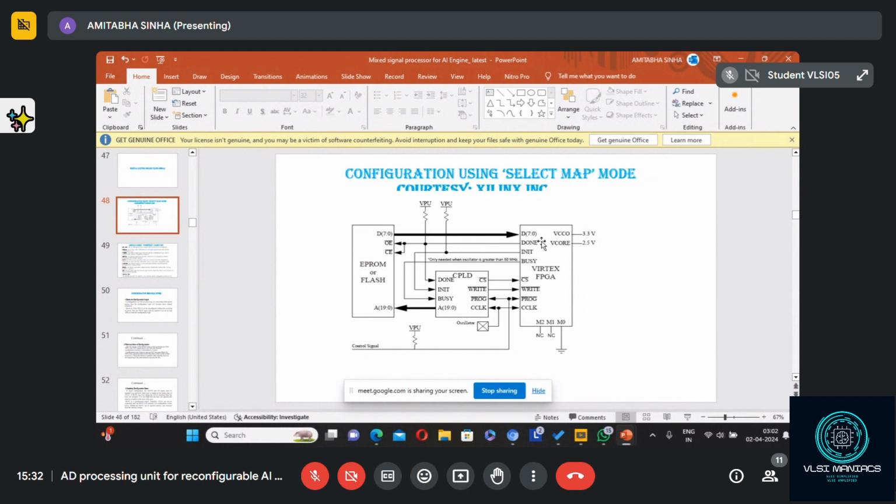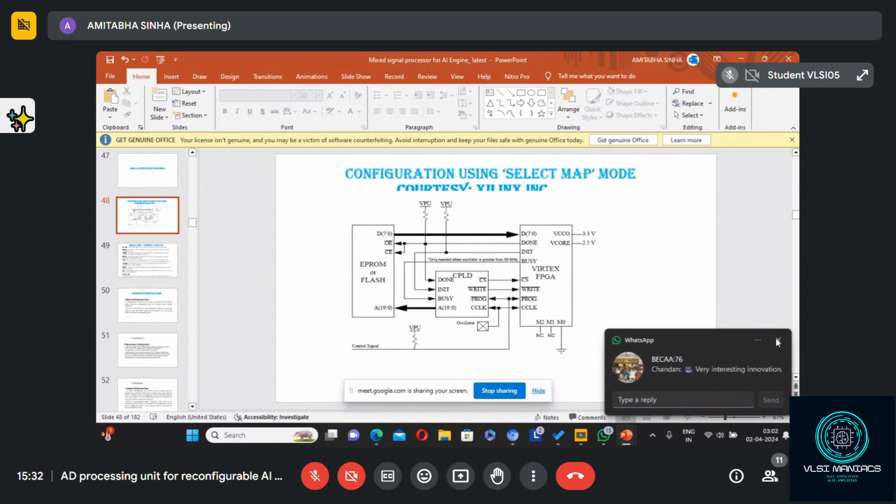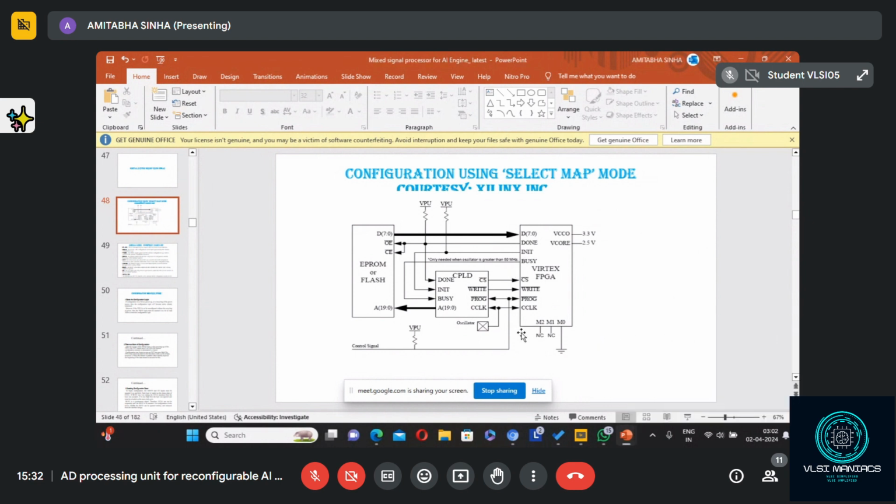Now again, what are the signals to be given by the CPLD? Once it gets the command from the CPU to program, the CPLD will make CS bar low to the FPGA, send the write bar signal low, and send the clock signal low. The clock is directly connected.